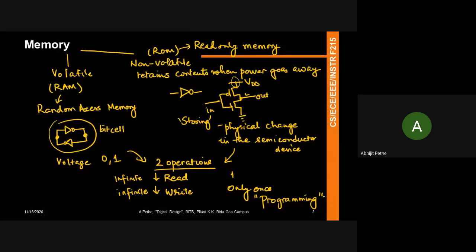You'd connect it to a specific board which had the same pins as your chip, and you use currents on those particular pins to program it. So in a ROM, you normally can write only once, whereas you can read any number of times. Because it's a read-only memory, you program it, and once you program it, you can use it an infinite number of times.